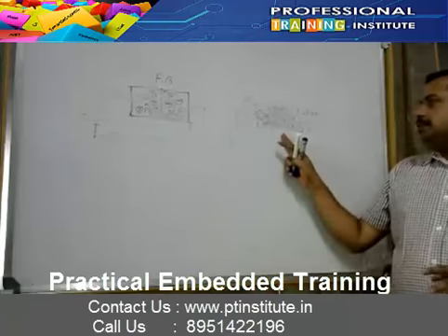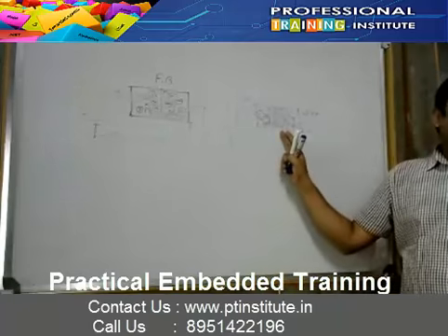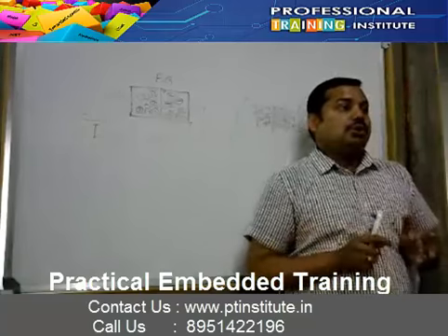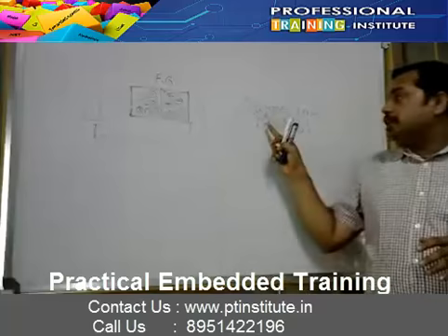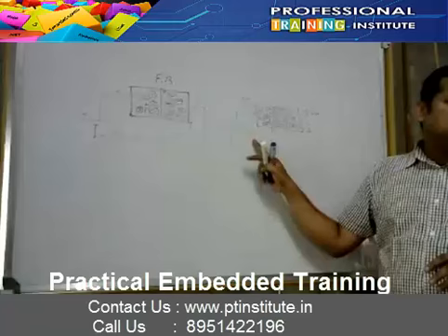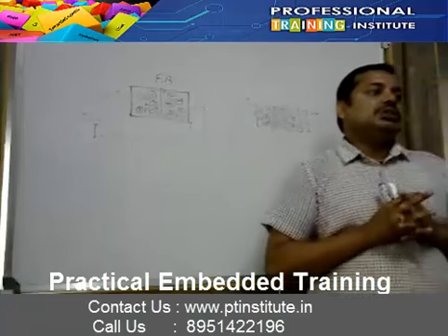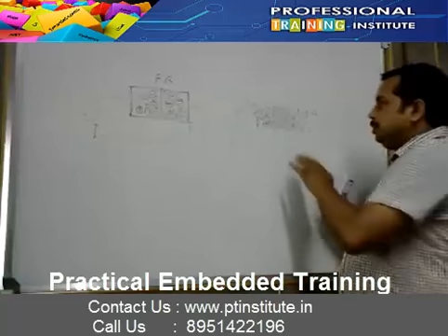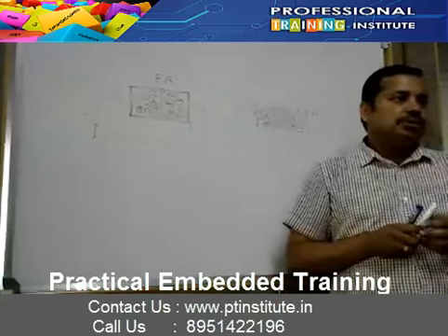Same thing is happening here. We are slowly building the depletion region, and at a certain period of time the depletion region is so strong that the electron does not have the capability to cross this, and the holes do not have the capability to cross this. They become an open circuit. Understand? So that's why current is not flowing.